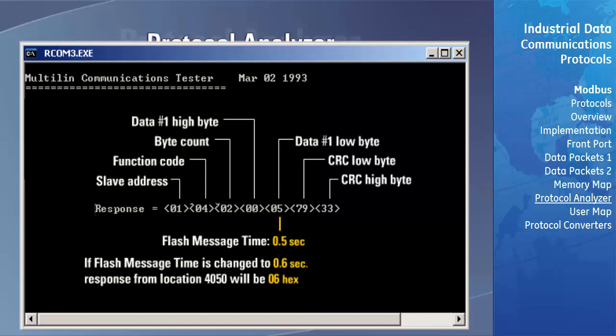If an error occurs, we'll get an error message and a beep from the computer. Under such a condition, the baud rate, serial cable, and serial communications port assignment in the computer should be checked, and once the fault is corrected, repeat the previous steps.